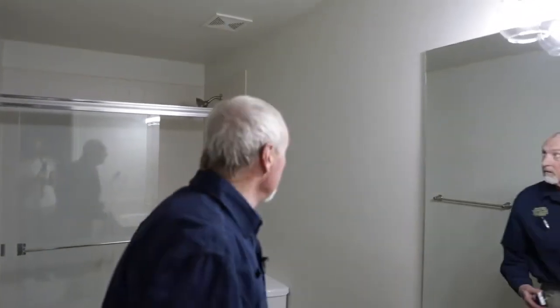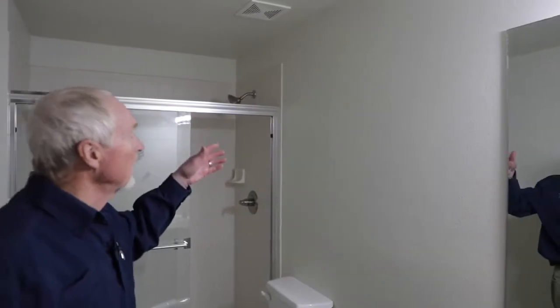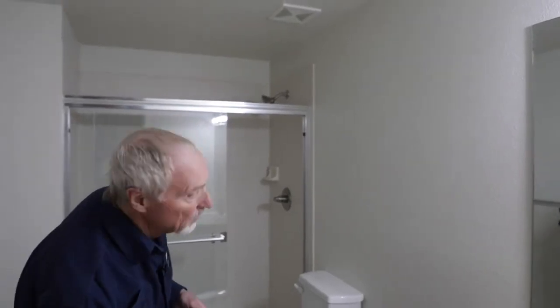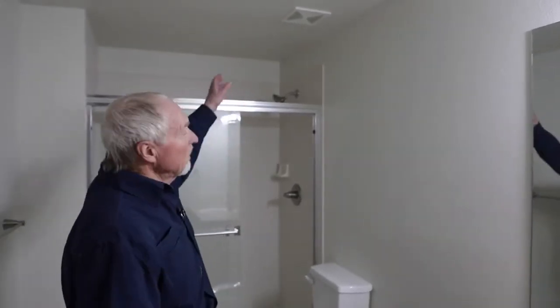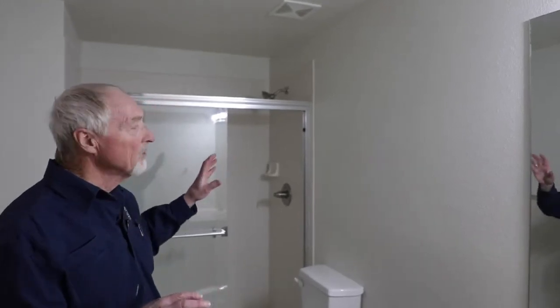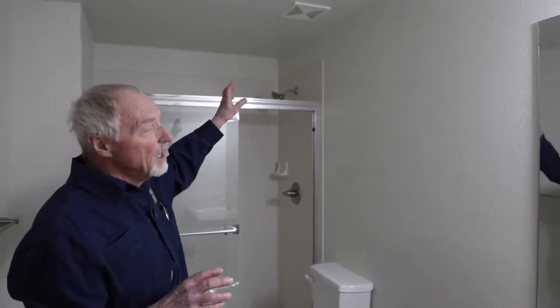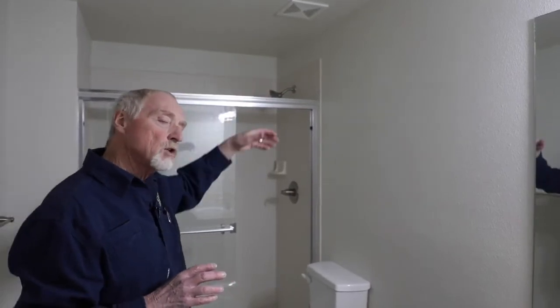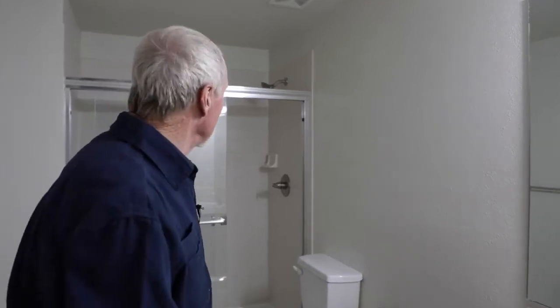Not required to determine if it's correctly terminated outside, but I'll usually look for that when I'm on the outside of the house to see if I can confirm that, particularly on basement finishes, more than other places in a house, they may not have ducted the vent fan to the exterior of the house like it is required to be. But right now, that looks good.